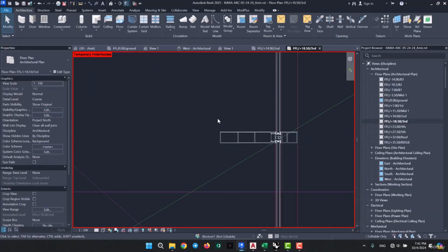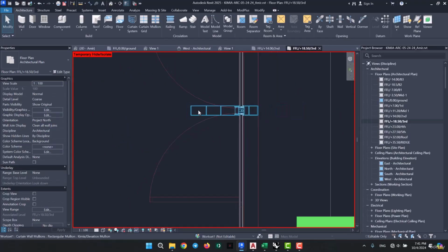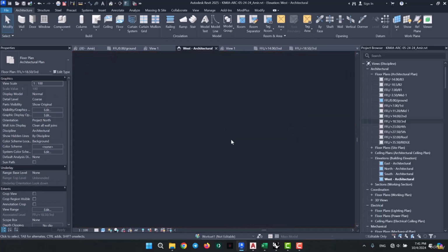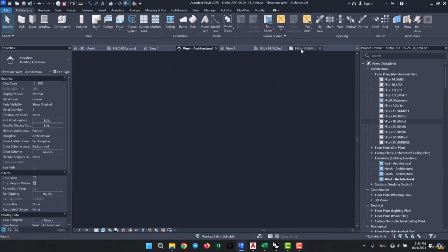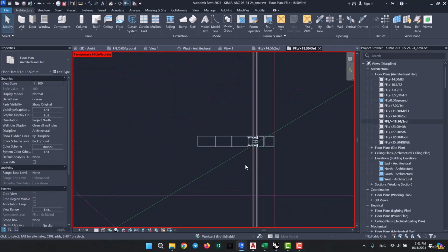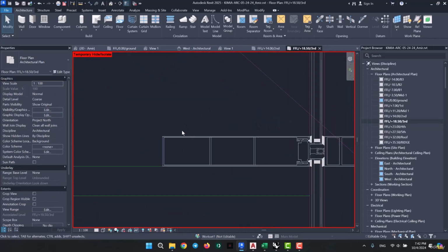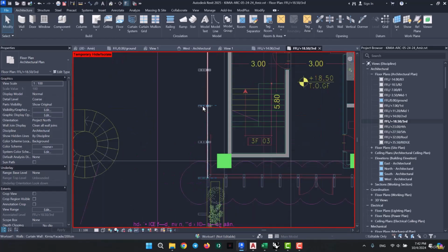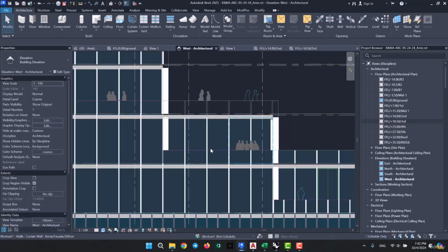And there we go. As you can see now, all the mullions are perfectly in their right places. And that's it. Now let's go back to the elevation and double check. And we can see that the breaks are fixed now. So remember to always start by checking the mullions on both ends, because oftentimes you might see that repositioning them or their grids can fix the problem, just like what we just did. So there we go, and this is basically how you can model and fix your elevations.